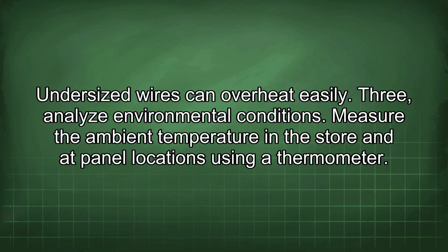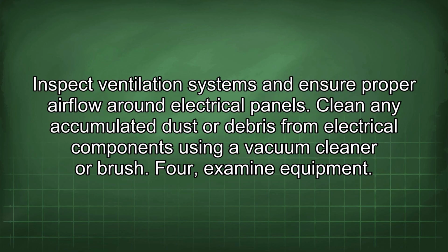3. Analyze environmental conditions. Measure the ambient temperature in the store and at panel locations using a thermometer. Inspect ventilation systems and ensure proper airflow around electrical panels. Clean any accumulated dust or debris from electrical components using a vacuum cleaner or brush.